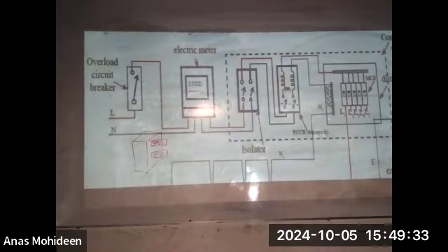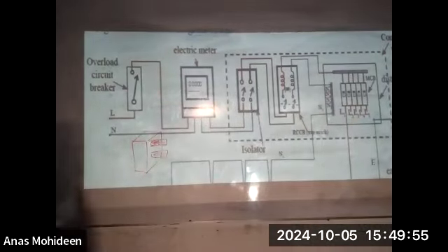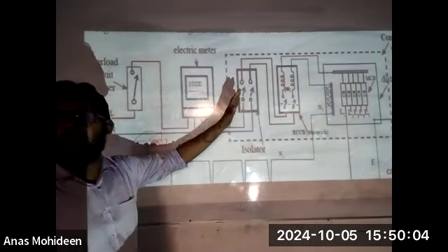Maybe because of repairing, renovation, or maybe because you are going out for a long term, or during flooding, or you have some electric repair work. During this time, you can turn off the main switch. So you can control it on your own, and moreover this also acts as a power barrier. An electric barrier for more than a maximum of 30 ampere. 30 ampere. Okay, so that is the isolator, the main switch.